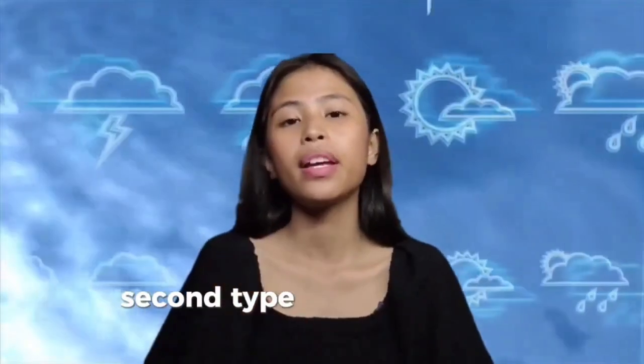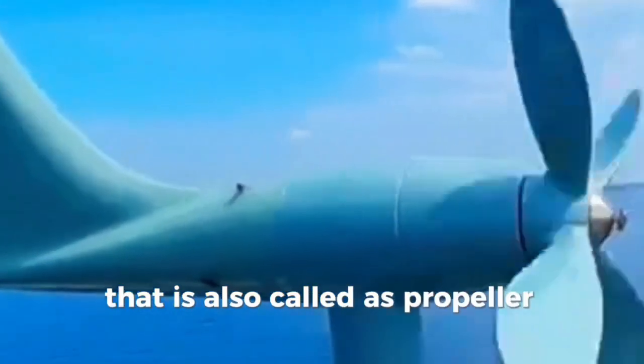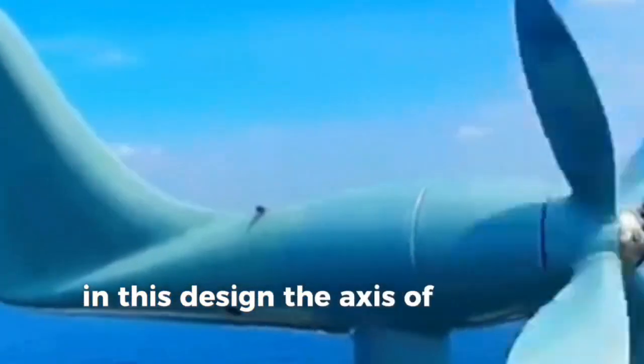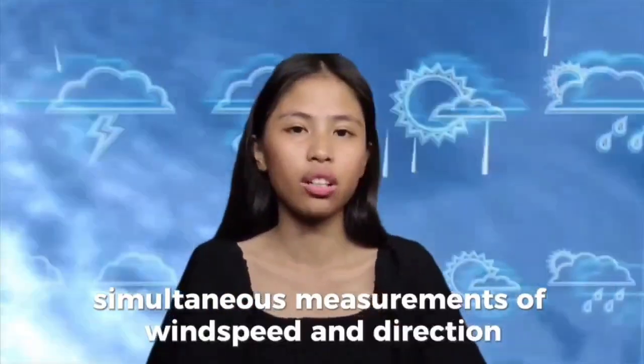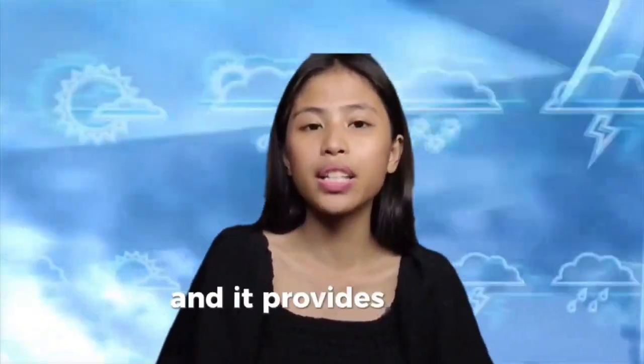The second type is the windmill anemometer. This windmill anemometer is another type that is also called a propeller anemometer. In this design, the axis of rotation is parallel to the wind direction, enabling simultaneous measurements of wind speed and direction. It is often paired with a wind vane, and it provides more comprehensive data for meteorological studies.